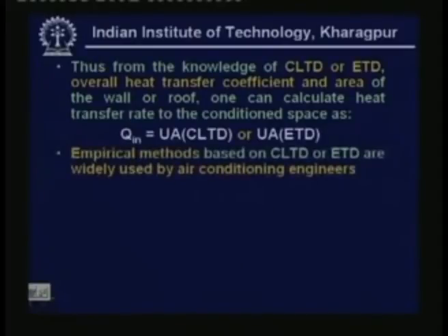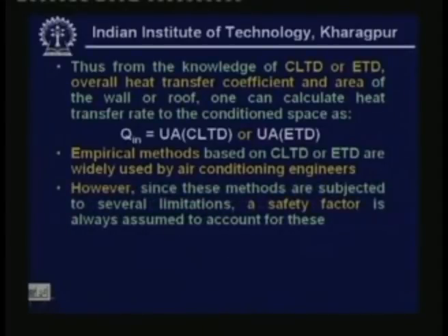Okay. Now, the empirical methods based on CLTD or ETD are widely used by air conditioning engineers. However, since these methods are subjected to several limitations, a safety factor is always assumed to account for these. Okay, so they are not 100% accurate, all these empirical methods. So, to take care of this, a safety factor is always assumed.